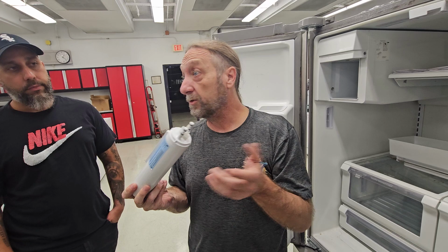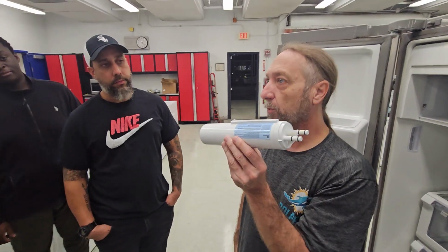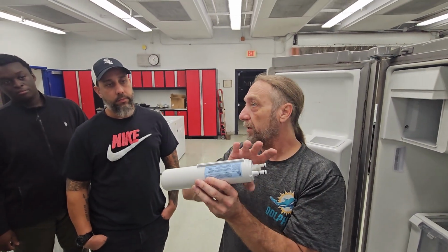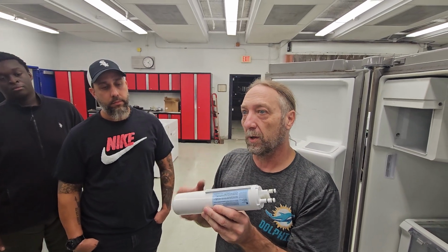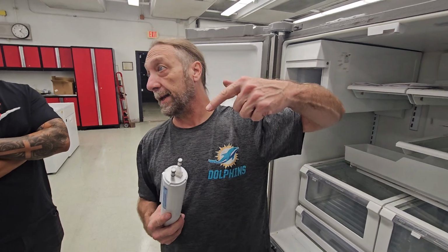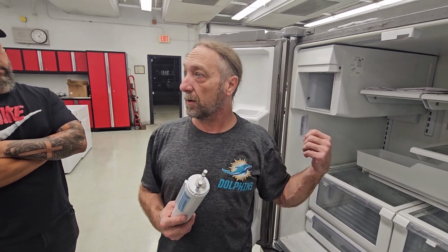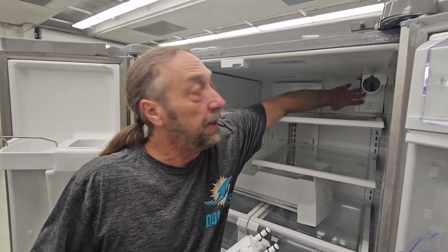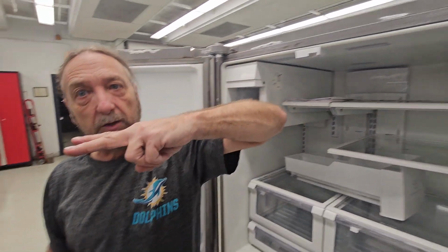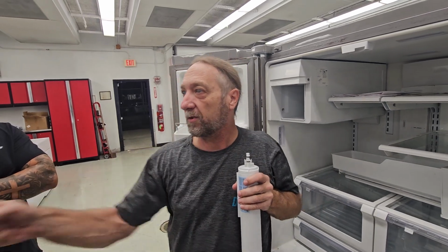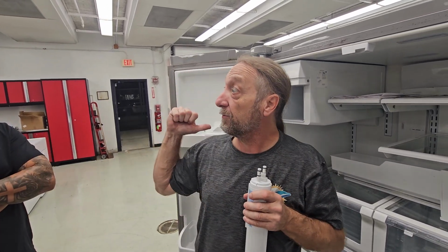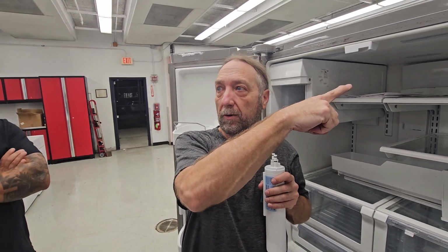You could go to someone's house and the ice maker and water not working, and you could have a frozen water filter, or you can have an older water filter that's blocked up and not passing water through. So when I'm talking about backtracking, is that if I thought my problem was at my water filter, when I take it out, there's something in there that prevents water from shooting out of here if I called for water on the door. Okay? So I would have to get back behind here, remove this component, and I would see those 2 lines and they're different colors, and I would disconnect the line going in, and I would press to see if I got water shooting there. That lets me know valve number 1 is pushing water up here.